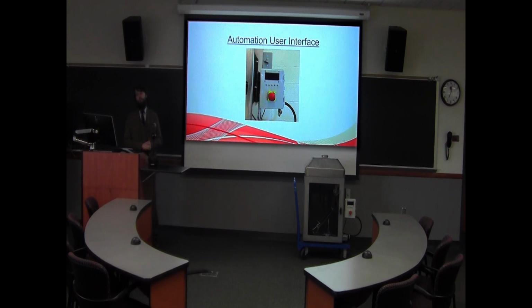Located above the control panel is a switch for the exhauster fan. This switch will be able to be wired into an inline exhaust fan on the exhaust hood to turn on the exhaust after the test so you can evacuate the smoke before you open the cabinet. Located at the bottom of the control panel is the needle valve for the fuel system in an easy to reach location so you can adjust the fine-tuning of the fuel lines.